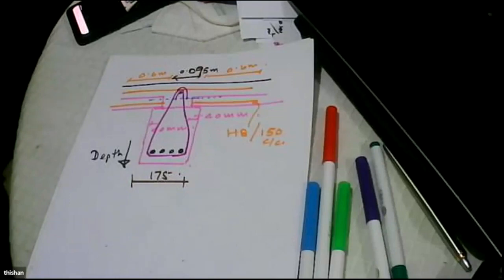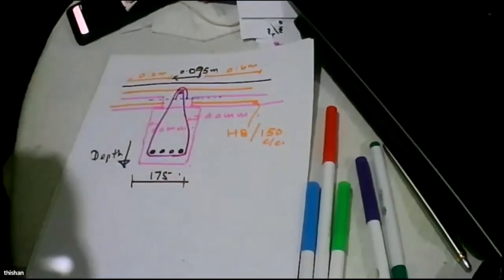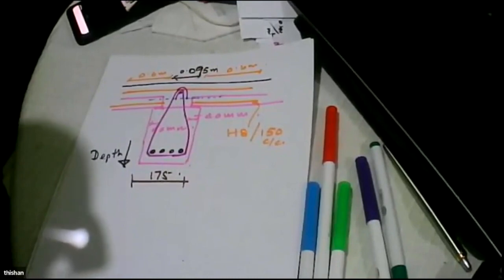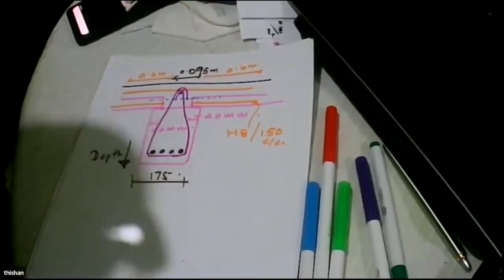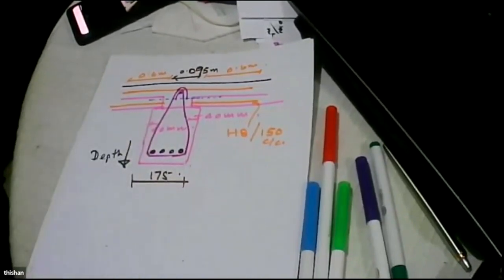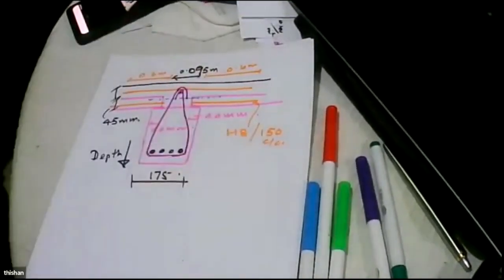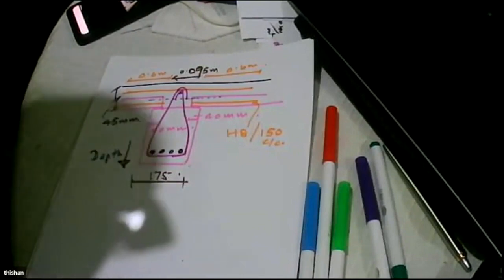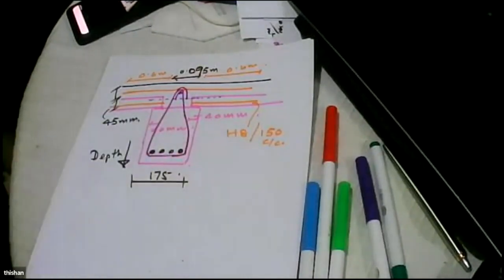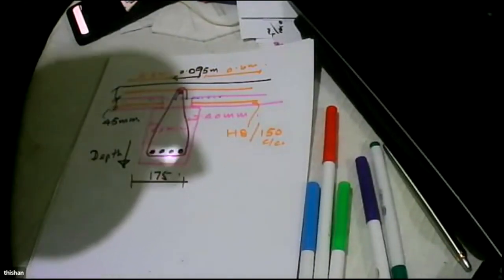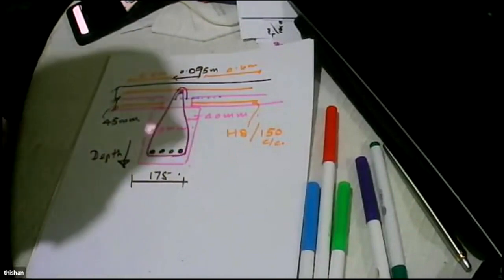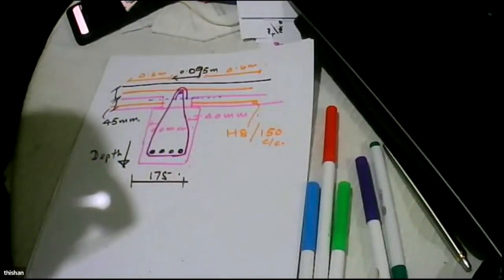Then depending on the span, in a similar manner, considering it as a flange beam, we can design the beam as well. That we'll discuss next day. But today I explained in detail how we arrived at 45 millimeters, why it is sufficient because the slab cover requirement is only 15, and why we had to use admixtures and go for high strength mix concrete when you are doing the precasting operation. So very significant cost savings can be made versus the traditional systems.